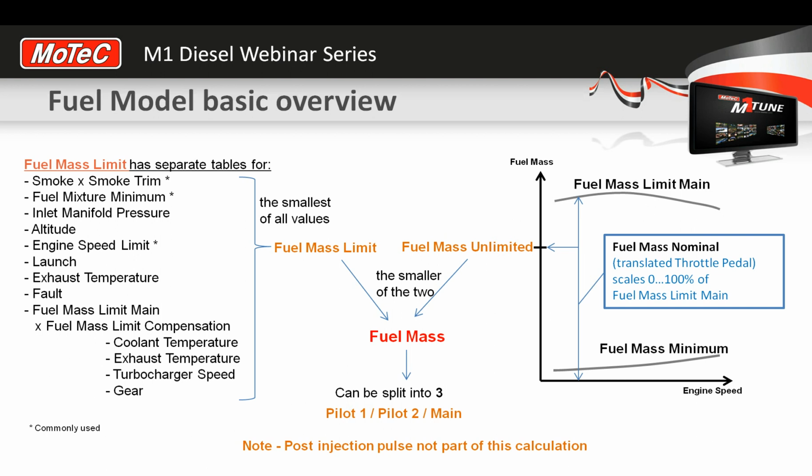Alright, does that make sense? I don't need to show you that table. It's still got mass flow or milligrams of airflow, the air mass, on its vertical axis. But you can, in most cases, normally get away with just a 2D table, which is proportional to engine speed. So just engine speed on the horizontal axis, and put in your lambda aim, and you're away.